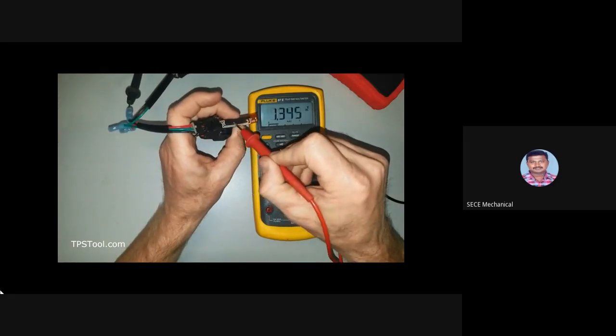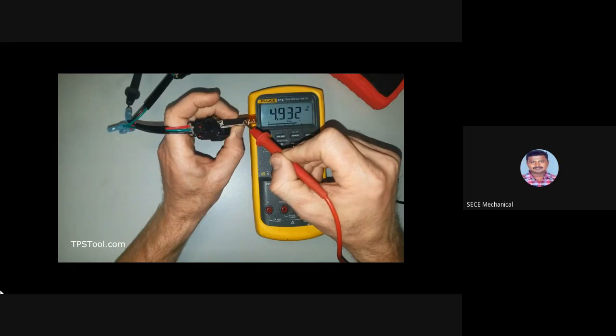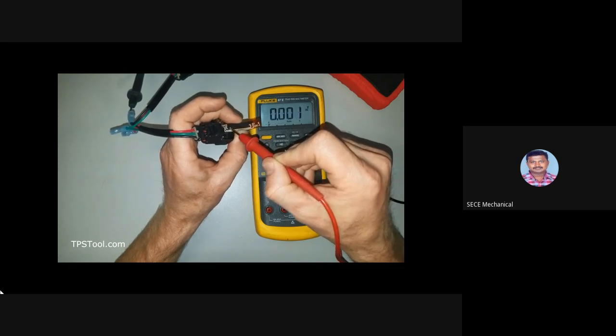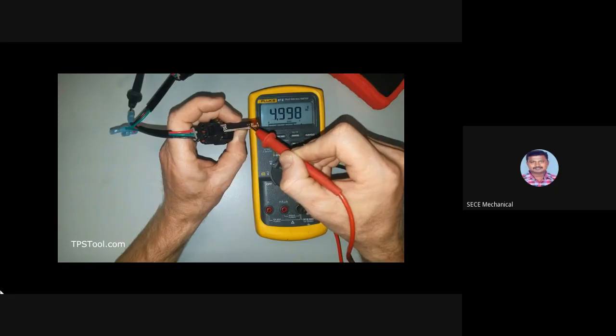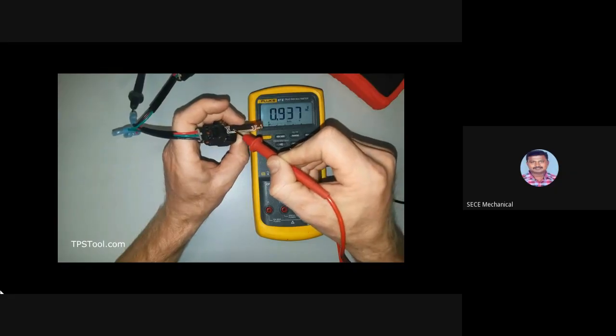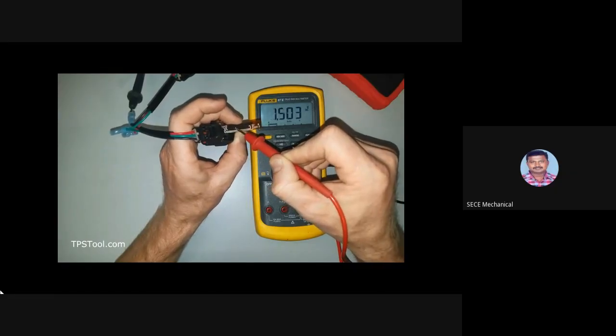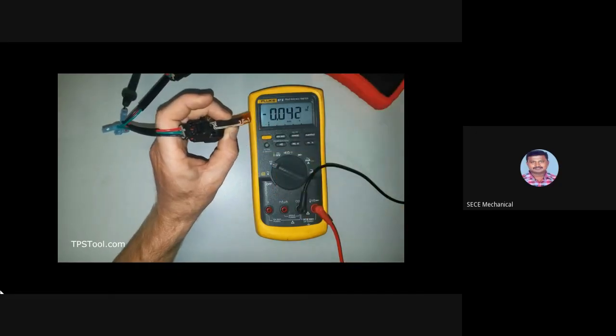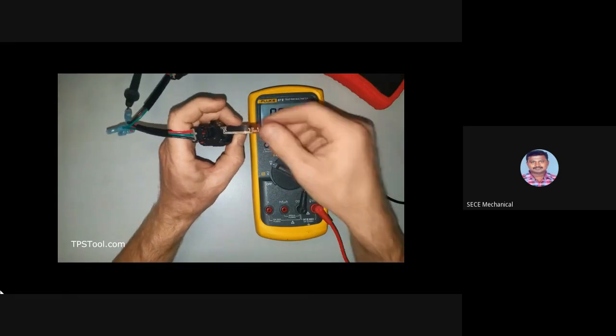As you come this way, that's full throttle, essentially 5 volts. And as I go back, you know, half throttle, you're somewhere in here. And as you go across this conductor, the voltage changes because the electricity loses energy, loses voltage as it goes across the conductor, as the resistance eats it up. So that energy is actually lost in the form of heat, but there's such a tiny amount of current that goes across that you really couldn't measure it.